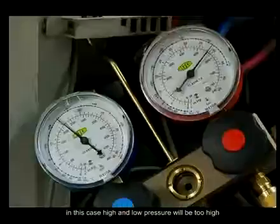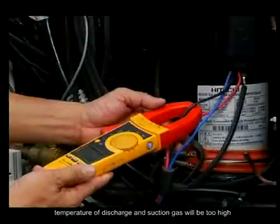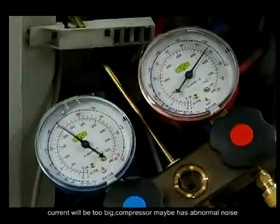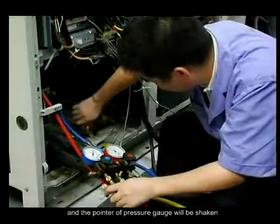In this case, high and low pressure will be too high. Temperature of discharge and suction gas will be too high. Current will be too big. The compressor may have abnormal noise, and the pointer of the pressure gauge will shake.